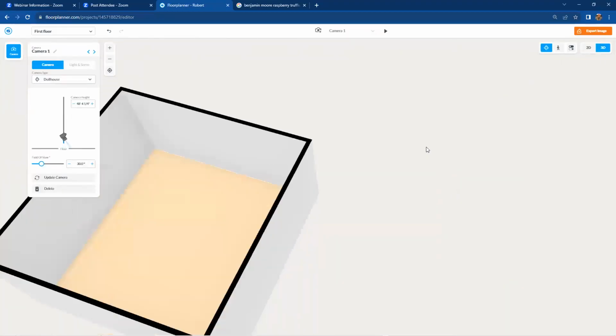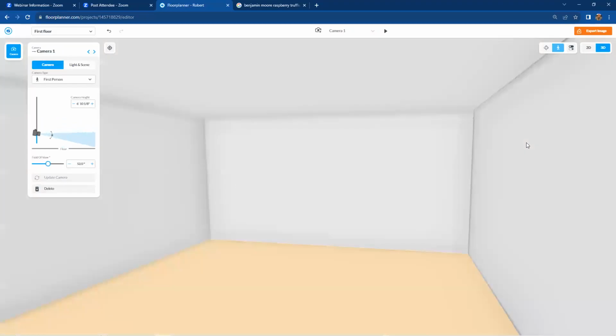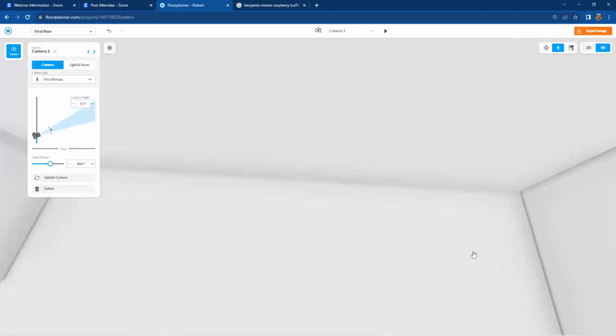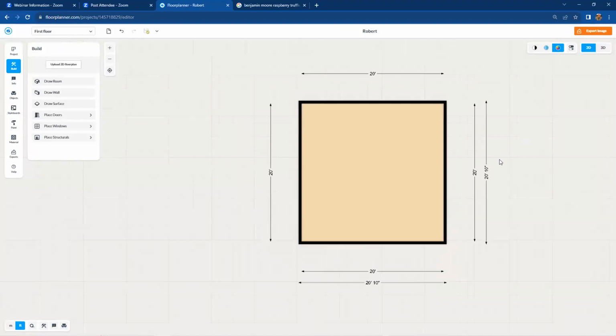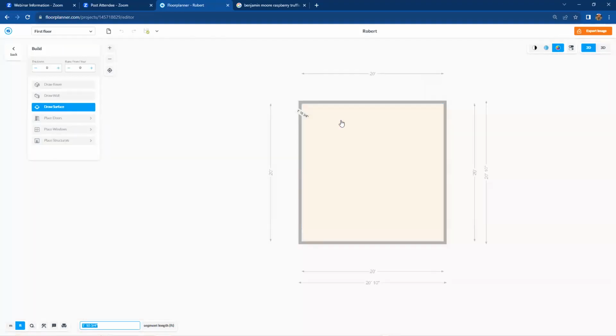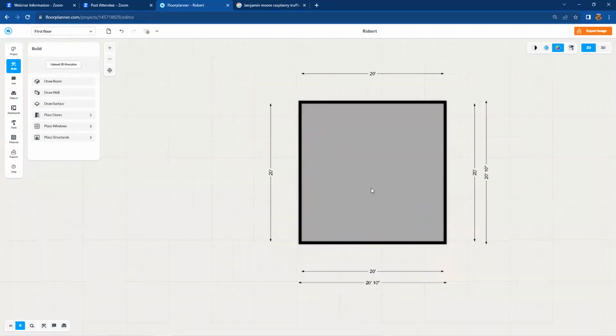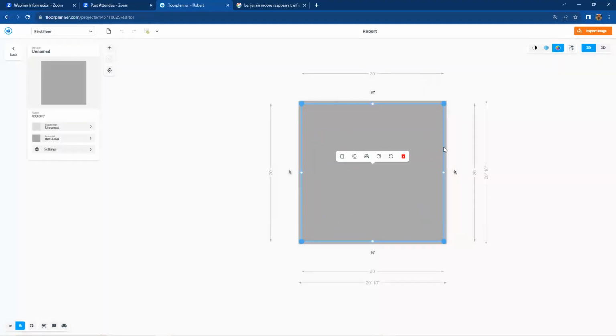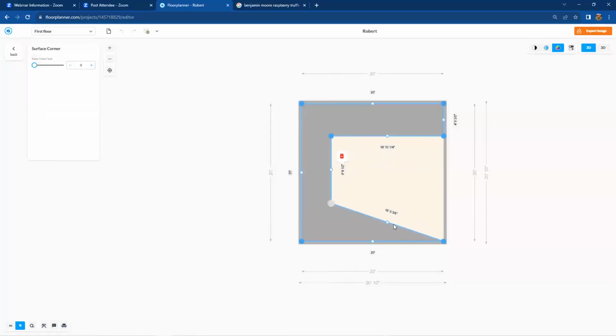Make sure it's still there. Looks good. Let's go inside our room. Flat ceiling. Okay, this is a 10-foot high ceiling. Let's talk about making a tray ceiling inside here. There's no reason why you couldn't draw a surface inside here and just start tracing at the same volume that we talked about earlier, like so. Now I can select this and maybe I'm going to put a tray in the center. I can make another point. Here is a grip. Another point. Here is a grip. Drag this one inward and start making a tray ceiling, defining where your tray is going to be.